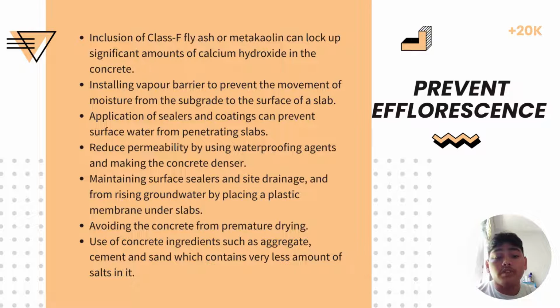Maintaining surface sealers and site drainage, and protecting from rising groundwater by placing a plastic membrane under slabs. Avoiding premature drying of the concrete can also prevent efflorescence on the concrete. Use concrete ingredients such as aggregate, cement, and sand which contain very small amounts of salts.